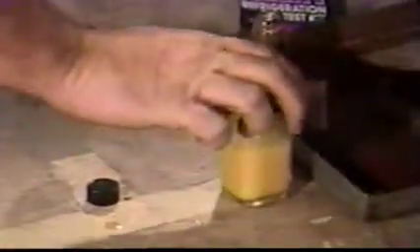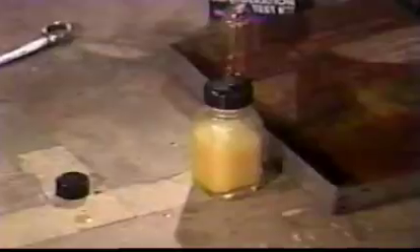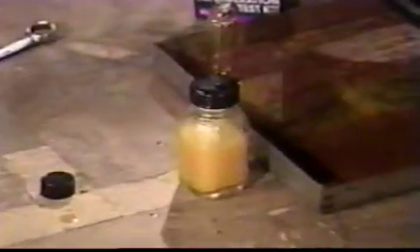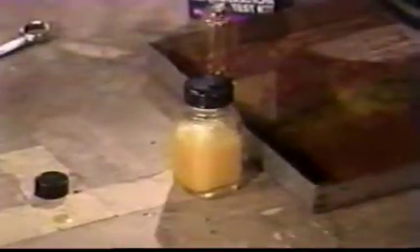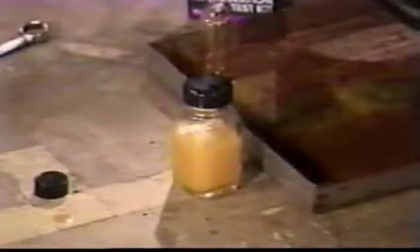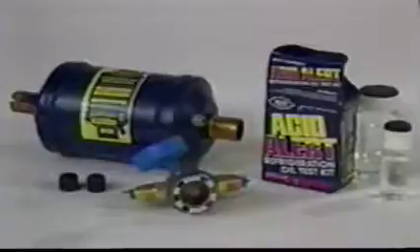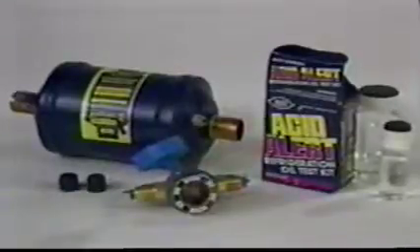In a compressor burnout, the amount of acid and other contamination is significant, and it is the filter dryers that must remove it. Depending on the severity of the burn, it may be necessary to replace the filter dryers after the initial startup. It is the Acid Alert Kit that will tell the technician when the acid level in a system is too high. In all the system protectors, the signals they send out can tell the technician a lot about the system he is servicing or installing.